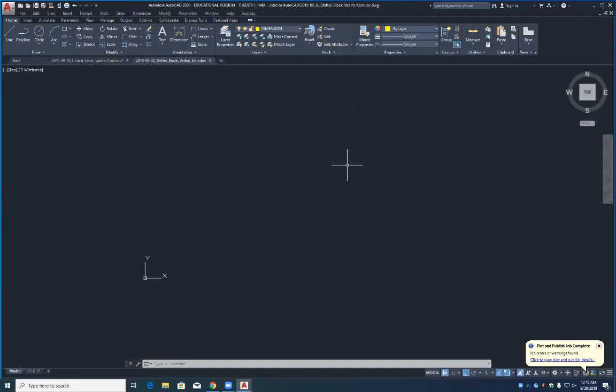Now, when you create hidden lines on a B-size drawing, if you draw on a D-size drawing and print it out on a B-size, it's going to be small, right? All your line types and gaps are a little bit smaller. What your goal is, no matter what size drawing you draw and print out, you want your hidden lines to be 100% the same length.